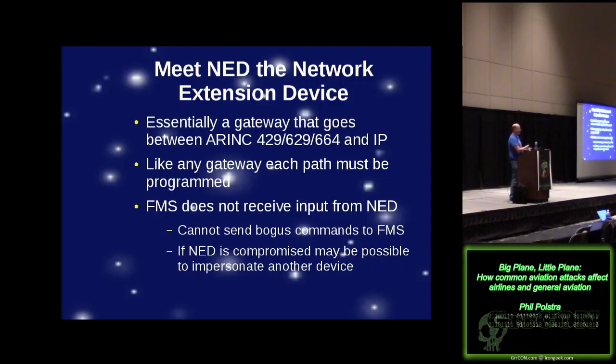In the case of a NED on your airliner, it's going to go between the ARINC protocol, whatever it is, and your garden variety TCP/IP that the in-flight entertainment system is going to use. So they're not talking the same language. It's a translator. And like most gateways, every path has to be programmed, right?